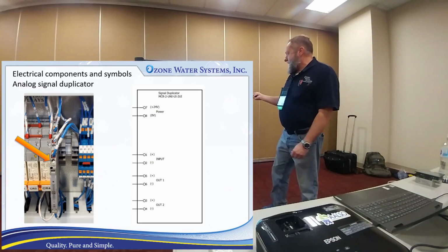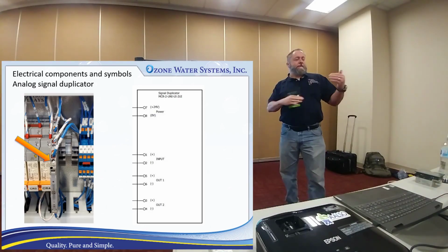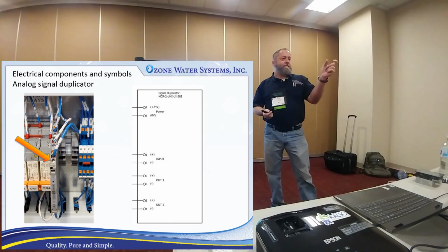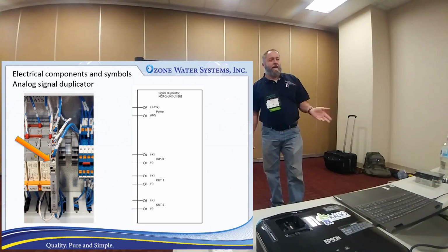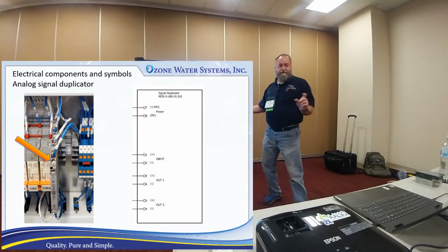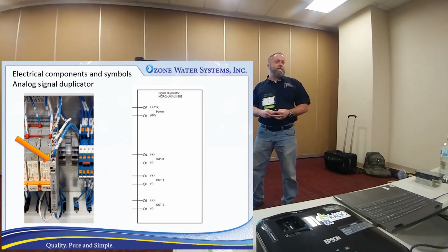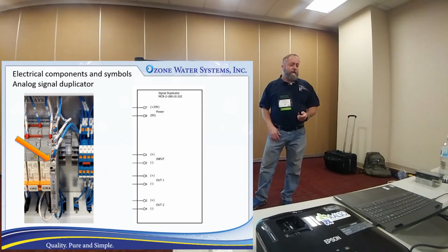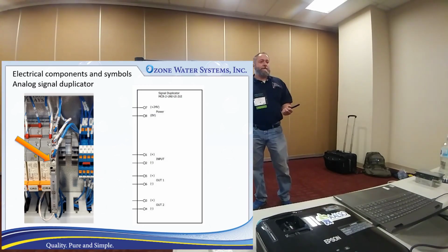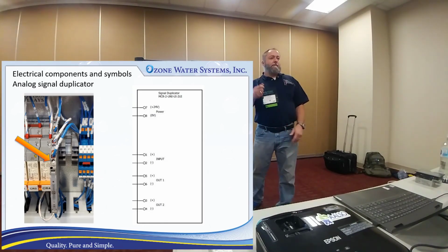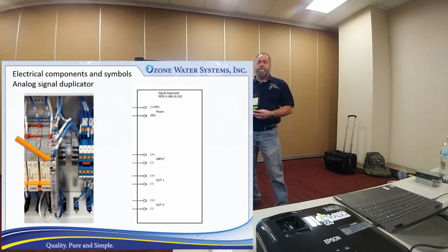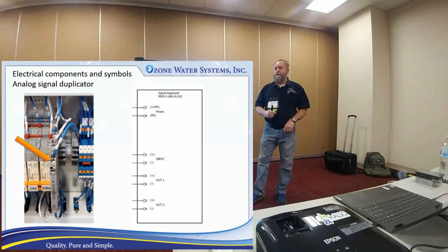It wouldn't be from an analog splitter. The analog is a variable control signal, so you can see a value like for your ORP goes from minus 999 to plus 1,000 or something like that. That's what this is going to do. And if you would just need an on-off signal for that, usually you're going to have, like for ours, the blue one is off of an ozone running, just an on-off status thing. So if you have a contact that turns on whenever you're making ozone, or whatever the parameter is you're trying to do, it just closes the contact.